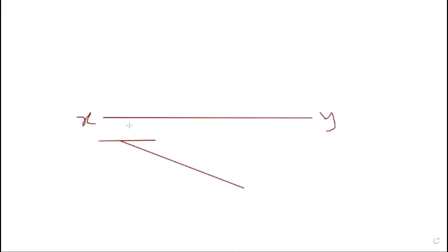And this distance will be the arbitrary distance. Now, because this is the top view, we write this point as small g and this as small h. And this GH will be 50 millimeter, because in the top view we see the actual dimension.